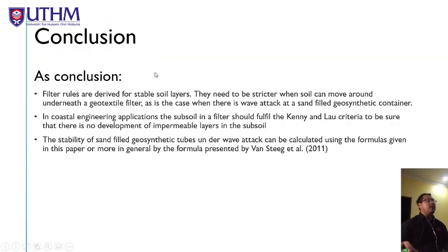For the conclusion, the filter rules are derived for a stable soil layer. They need to be stricter when soil can move around underneath a geotextile filter, as is the case where there is wave attack on a sand-filled geosynthetic container. In a coastal engineering application, the subsoil in a filter should fulfill the Kenney and Lau criteria to be sure that there is no development of an impermeable layer in the subsoil. The stability of the sand-filled geosynthetic tube under wave attack can be calculated using the formula given in this paper, or more in general by the formula presented by others. That's all from us.